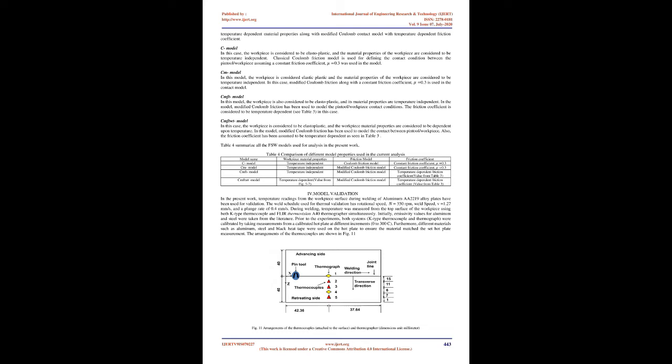Contact properties. During FSW, sticking or sliding occurs between the materials in contact, workpiece and pintool, depending upon the contact shear stress. While sticking, material near the surface adheres to the pintool. The velocity dissimilarity between stationary material and materials moving along the tool causes shearing action. The determination of the contact friction stress is different in the two contact models, Coulomb friction law and modified Coulomb friction law. According to the Coulomb friction model, no relative motion occurs if the equivalent frictional stress is less than the critical stress. The equivalent friction stress can be defined by equation 24.